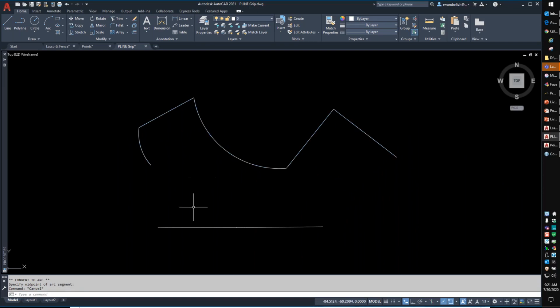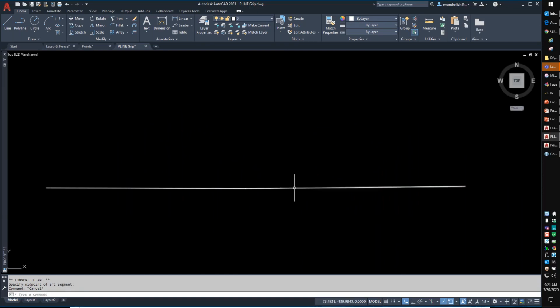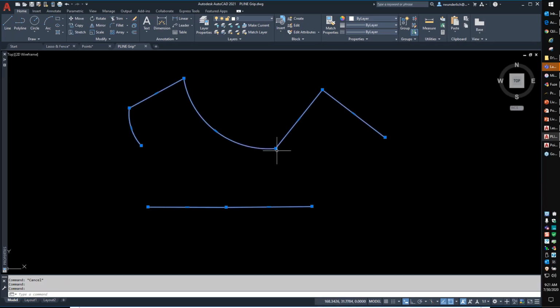Now, one of the things I want to show you, and this is one of the key things that I run across with people doing polylines. I have a polyline here that is a single segment that has this and an end vertex that has this. This middle vertex, you'll see, does not pop up a dialog box. You will also see that I have 3 dimension values in here. I have my 232, my 255, and then a value of 0. What this means is that at this exact point, there are 2 vertices right on top of each other. So if you are ever in a situation where you're clicking on a polyline and you cannot get this dialog box to pop up, most likely you have duplicate vertices here.